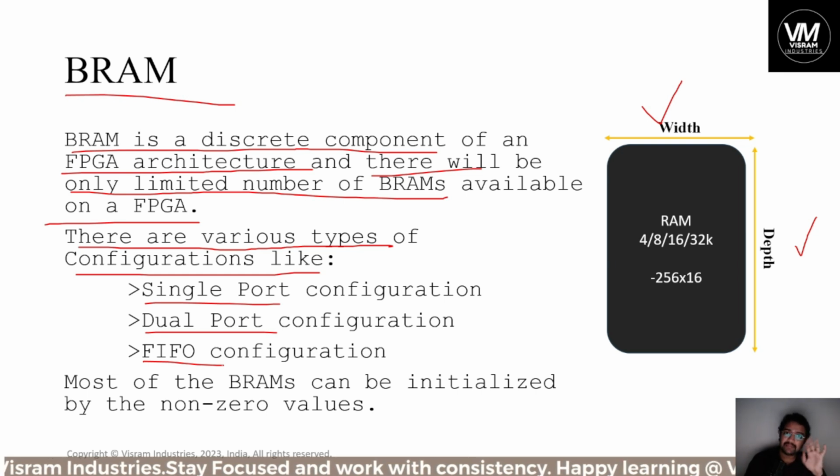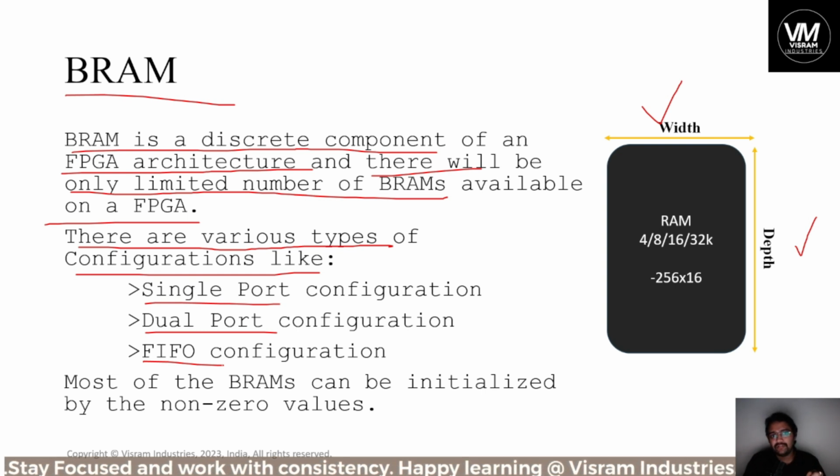But when the number is limited, you should use the BRAM wisely. Are you using them only for FIFO and leaving the rest unused for any other data transition? No, you should use them wisely. If you require only one FIFO, turn one or two BRAMs into FIFO and use the other BRAMs in another application in your project. You should use them wisely when they are limited.